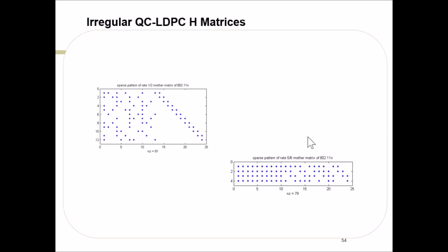He decodes each of those little short checks individually, and that's where he gets the minimum. For every one of those codes, he calculates a minimum and a second minimum. Based on that, he feeds back to the 8 or 16 bits in that code what he thinks they should be. They're each in about 3, 4, 5, 6 codes. Those go to the other codes and tell them what they think they should be, and then send them back again. He does that 50, 60 times, and you figure out what it is. That's what they do, but you have to live with it a little bit to follow that.